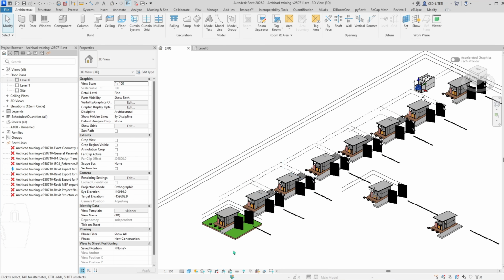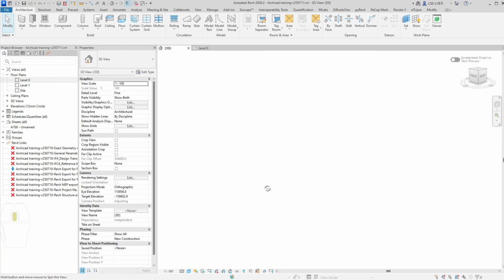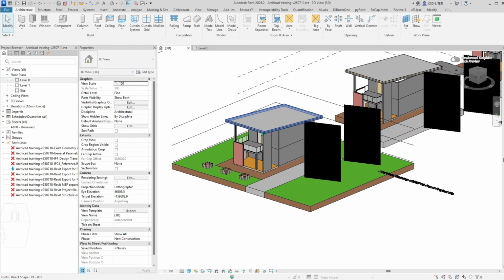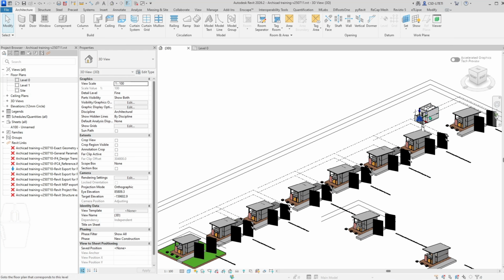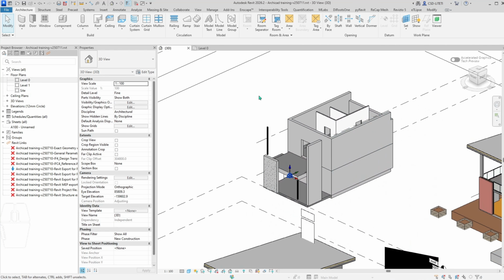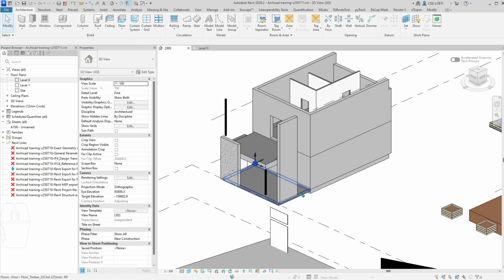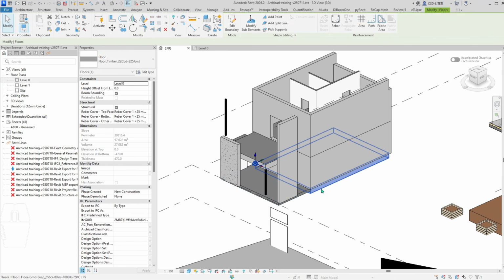As an additional option, if I would like to get full transformation and get the full result like I have here, it means I need to do some specific modifications inside the classification of the ArchiCAD model. So all the terrain elements should be converted to the classification of floors.